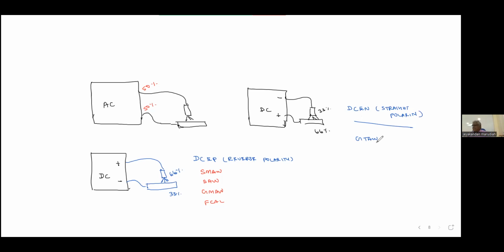Next one, we need protection to protect the weld from the atmosphere. Again, there are 2 types of protection. One is gas shielding. Which processes use gas shielding? GTAW, GMAW, FCAW can have gas shielding. Without gas shielding also you can weld. What is the advantage of gas shielding? Gas shielding processes are considered low hydrogen processes because there is no flux, there is no moisture.